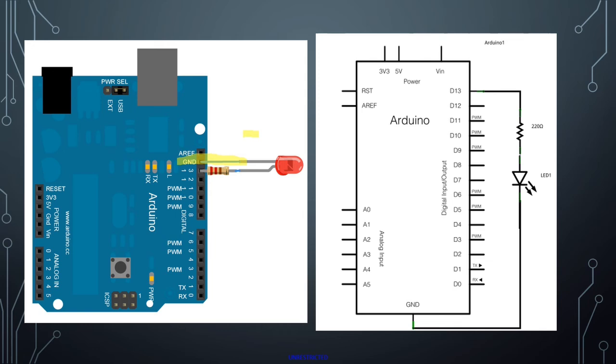So if you have anything with an anode and a cathode, you usually want to make sure that you are grounding the negative side of that. And then that puts our anode side over here. An easy way to remember that is that the negative side is the straight wire on the LED, which is the same as the negative sign, right? And so that's what I use to help me remember which is which on an LED, because I know sometimes it can be confusing. So we'll want to connect the cathode to our ground.